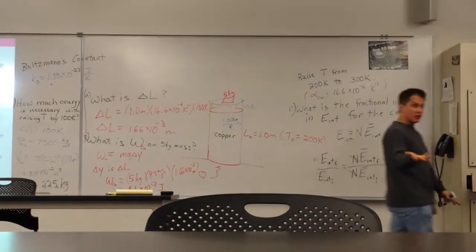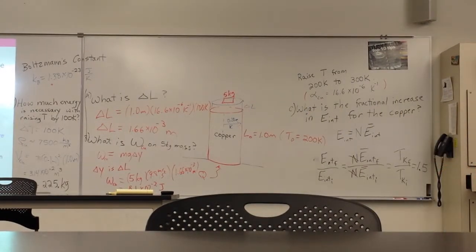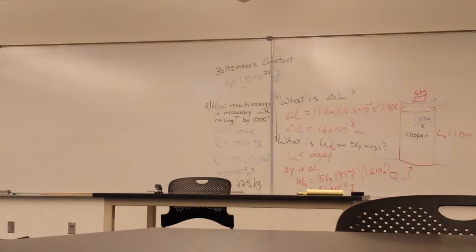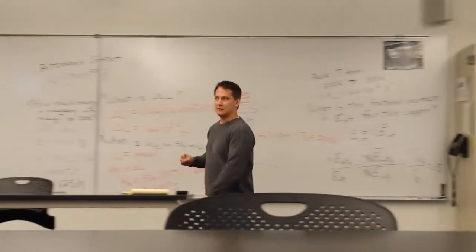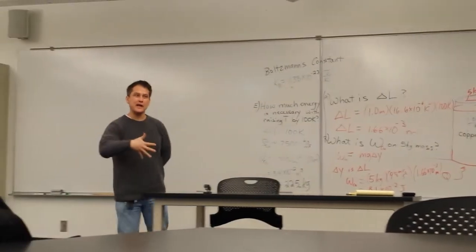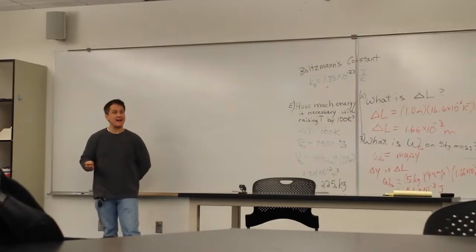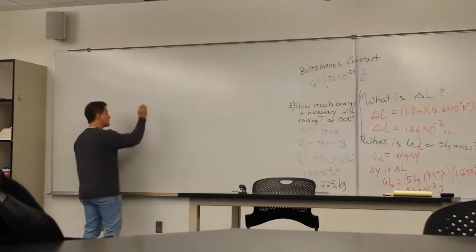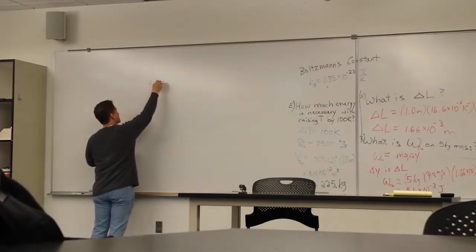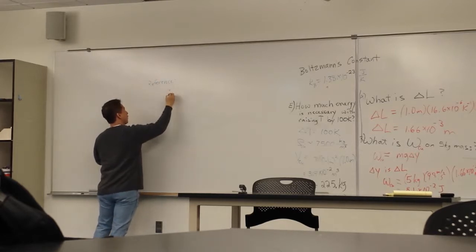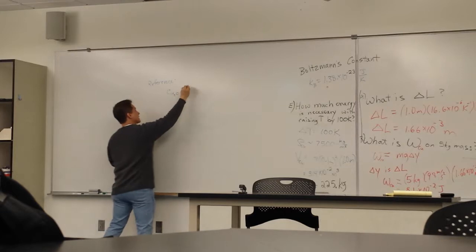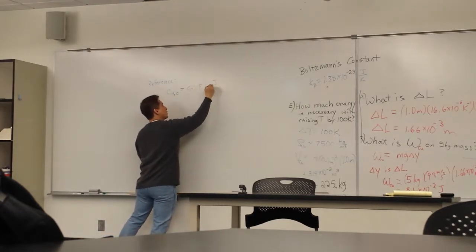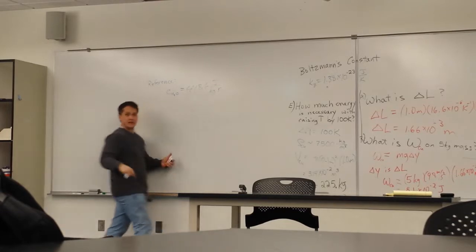So Q, and now we need to know what the specific heat capacity is. How much energy does it require to raise the temperature? I know one thing. I might even have a value here. Of course I don't. That'd be too easy. Basic conceptual information. Metals have heat capacities that are about 1/10 of water. Water has a huge heat capacity. So just as for reference, capacity for water is 4,186 joules per kilogram Kelvin temperature change.